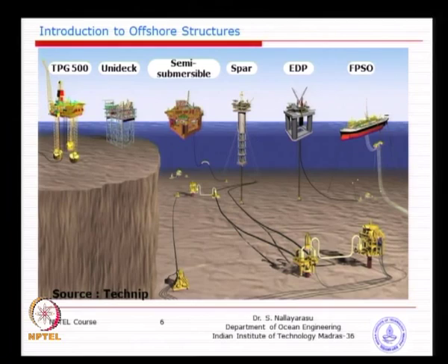In case the field is exhausted, you could disconnect and go to another project or another field with simple modification to the topside equipments. You may not use it 100%, but at least you can relocate the hull and the equipments without spending too much money, whereas for fixed platforms, the relocation actually becomes costlier than the installation itself.